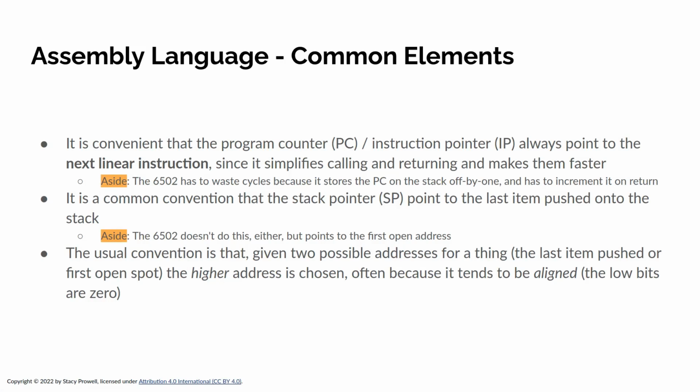It's a common convention that the stack pointer will point to the last item pushed onto the stack. Not everybody does it exactly that way. 6502 doesn't do that. Instead, it points to the first open address. So basically, it stores and then decrements, as opposed to decrementing and storing. Turns out there's some good reasons to do it the other way.